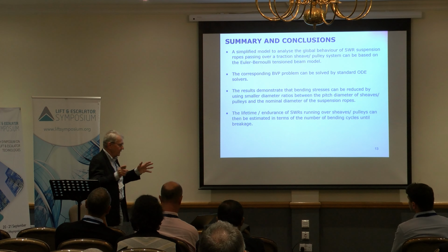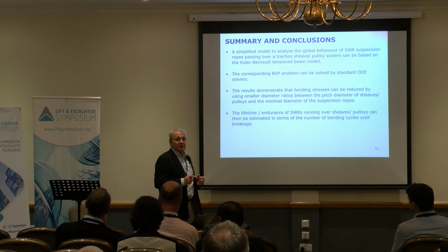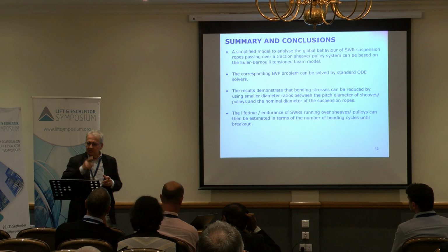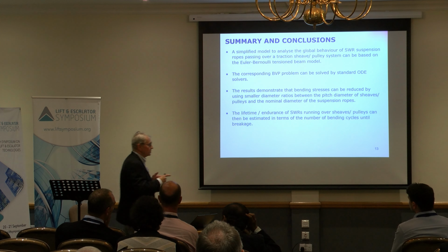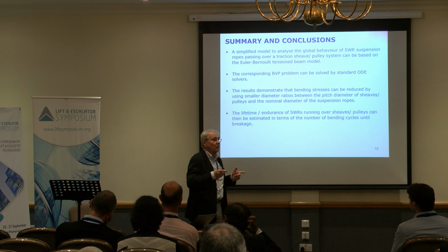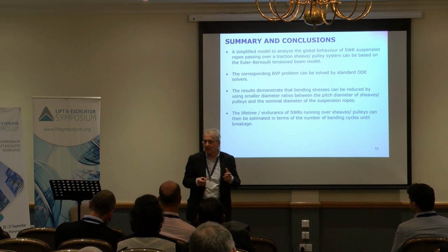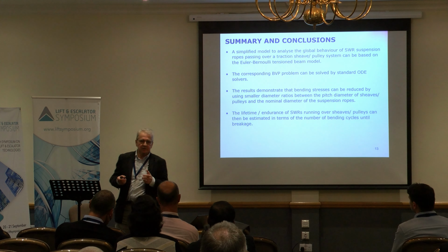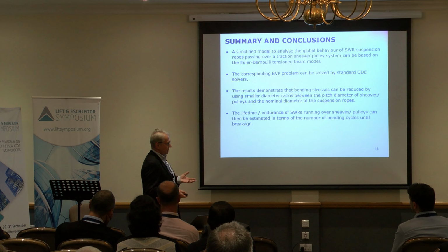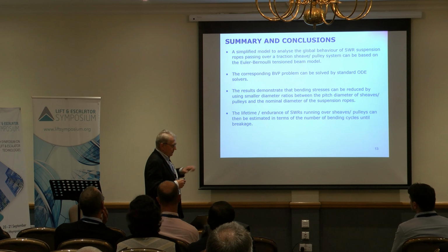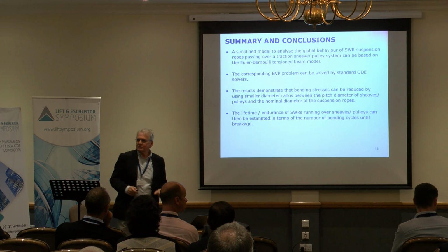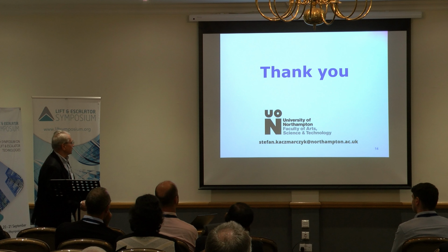That's okay, okay? Assuming that they are highly tensioned. However, if the ropes are not highly tensioned, we would rather use bending model which accounts for bending stiffness. For example, for compensating ropes. Compensating ropes are less tensioned, and then probably the results will be more accurate. So again, thanks very much, and that's about it.